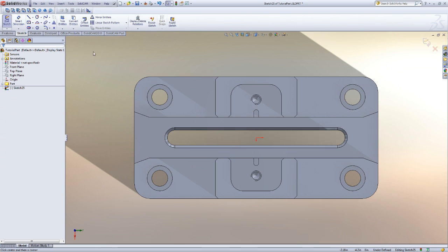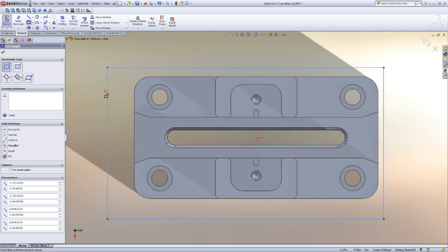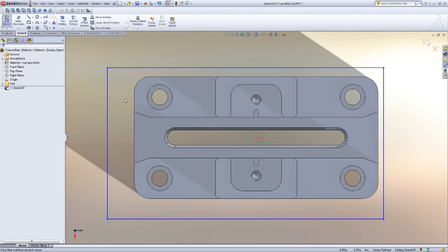And also, you may not want to assume that the part's drawn on center, even though it looks like it is. One way around this is to just sketch a rectangle around your part and have the four sides of the rectangle meet the extremities of your part.